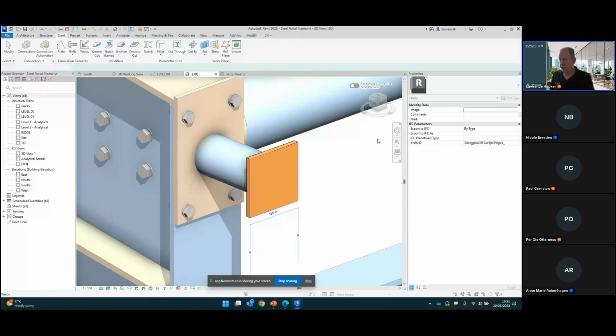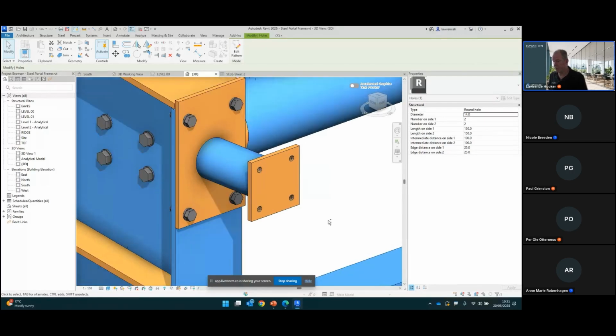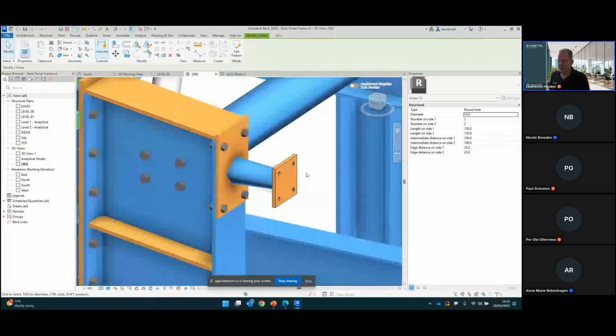As you probably know here, those holes will be created on the corners, but of course we can then go through and refine that setup in here. So I'm going to go for perhaps 100 millimeters inside there. Okay, we can see now we've got a slightly better arrangement, and we'll just change the diameter to 14. So that'll be for an M12 bolt with a 2 mil clearance. Okay, so there's my custom connection.